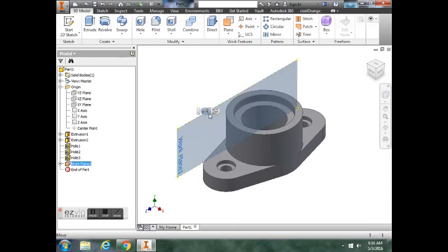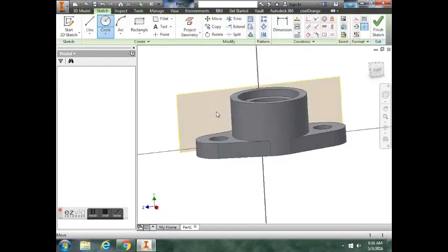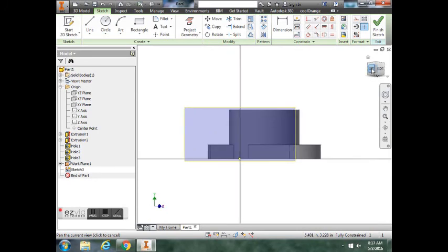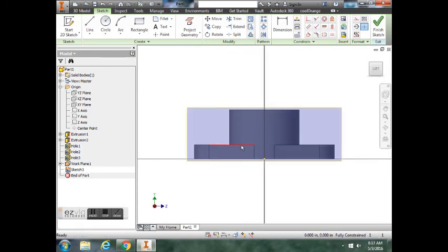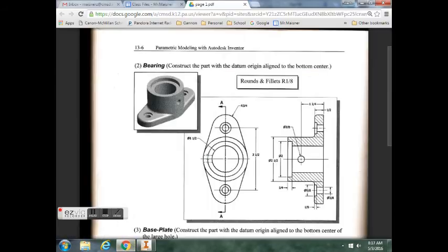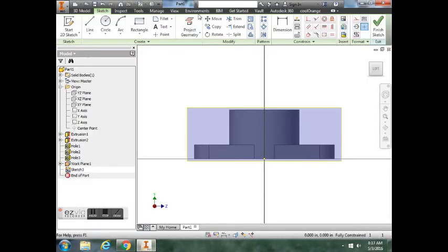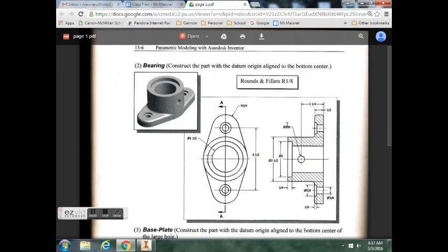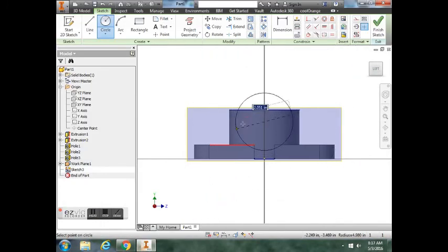Now we can click on the work plane, create a sketch. Make sure that you rotate around till you get to this left side view. Now we can draw a circle on this side of our view and extrude it through. So we're going to come up here to circle. Kind of like off of this center point, we're going to move up, draw a hole, or a circle I should say, that is 3/8 of an inch diameter. So it's centered this way.